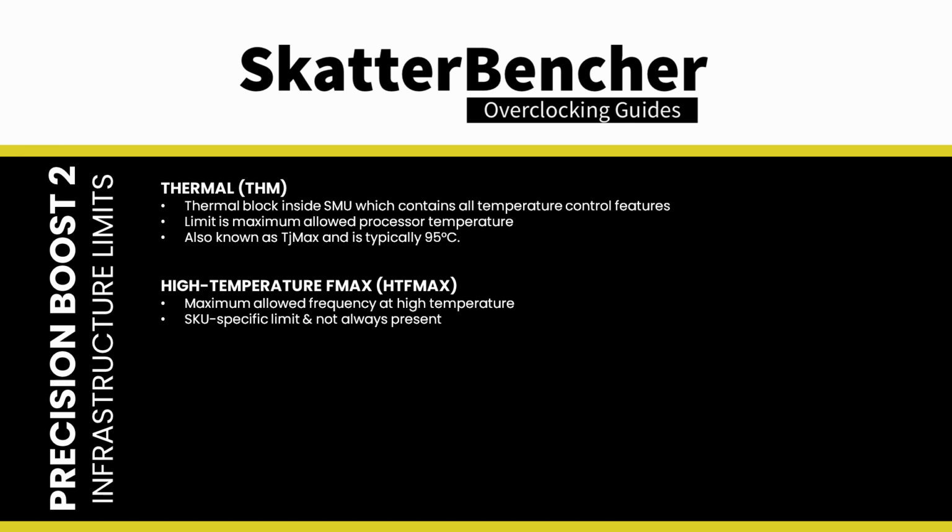High temperature Fmax, or HTF max, represents the maximum frequency allowed at high operating temperature. This limiter is SKU specific and may or may not be present. For example, on the 7600X, the HTF max limiter starts at 5450 MHz at 70 degrees Celsius. The frequency reduces linearly until it reaches 5150 MHz at 95 degrees Celsius. However, on the 7900X, this limiter does not appear to be present.